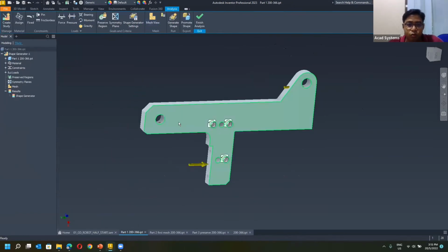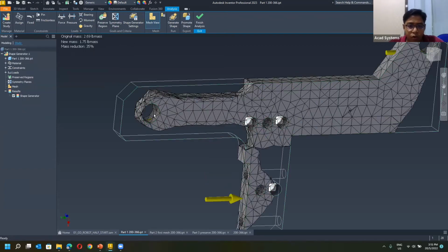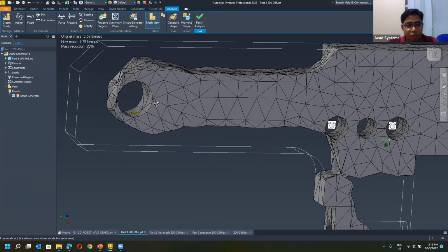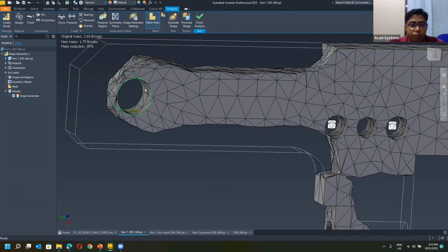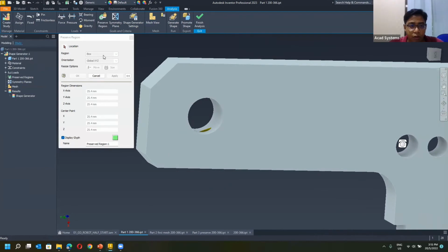For that case, you have what we call preserve region. With preserve region, it will generate and try to retain the region that you have selected. You can find the tool under goal and criteria. So we have preserve region. What I'm going to do is make sure the area over here is slightly larger, so I'm going to reserve some of the material from this area. I can use preserve material, and over here I can select the faces.